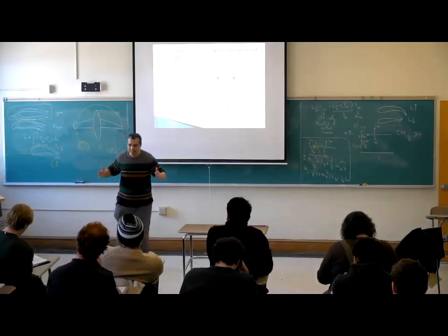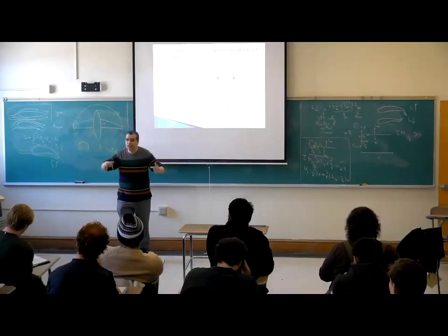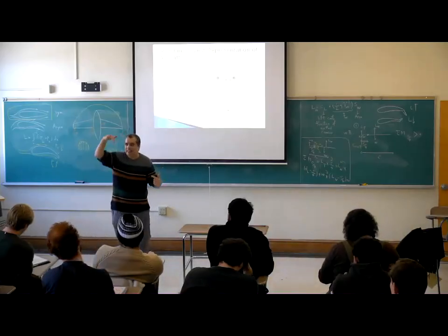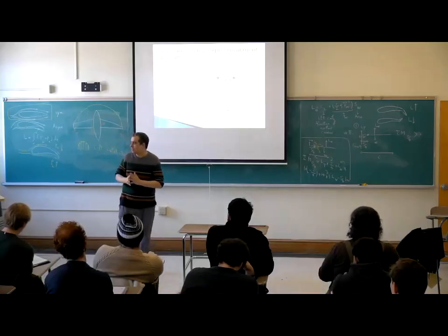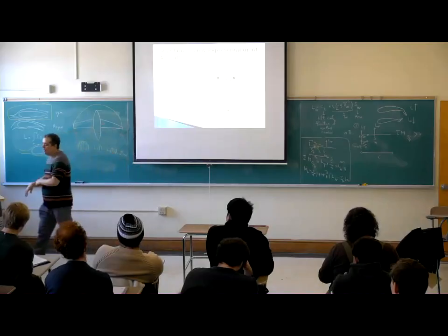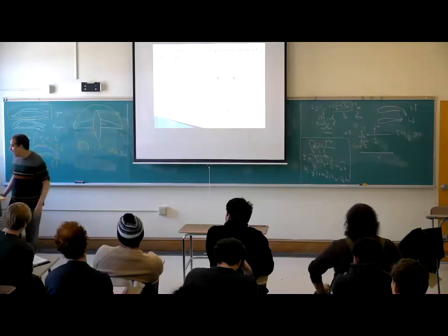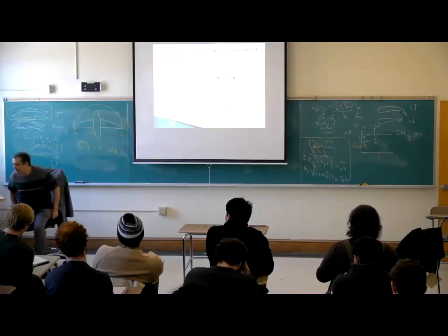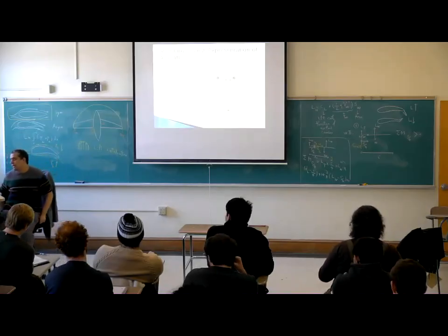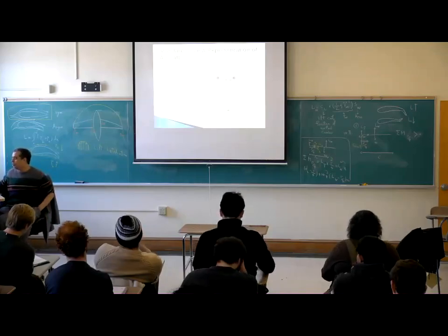When you have high lift at the root, increase the area. Because the structure should sustain the lift. Because the lift is something going up. Okay? If the structure is not strong enough, the structure will be damaged. The Wright brothers used a very thin airfoil because they didn't have a very lengthy wing. But if you use a lengthy wing, you require a very strong body.